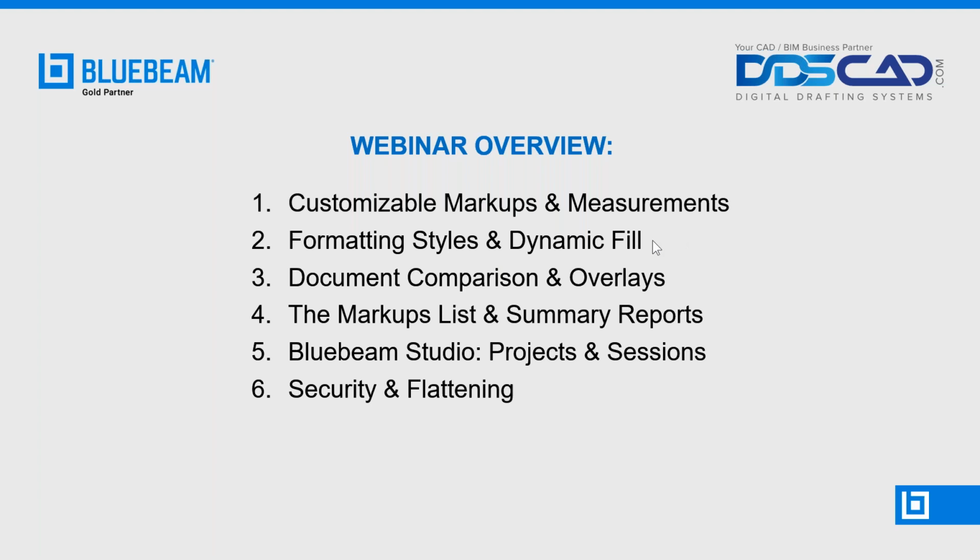I might have shown this to you guys in previous presentations, but I always get a kick out of sharing it. The document comparison and overlay tools are essential, especially in the construction industry, and I'll be showing you guys the difference between the two and how you can use them both in conjunction. The markups list and summary reports will also help us to organize our markups, and then you can make some hyperlinked reports. Today, I'm going to show you how to make an Excel summary report, which is a little different from the PDF one, but it takes your information and puts it directly in Excel in two different ways.